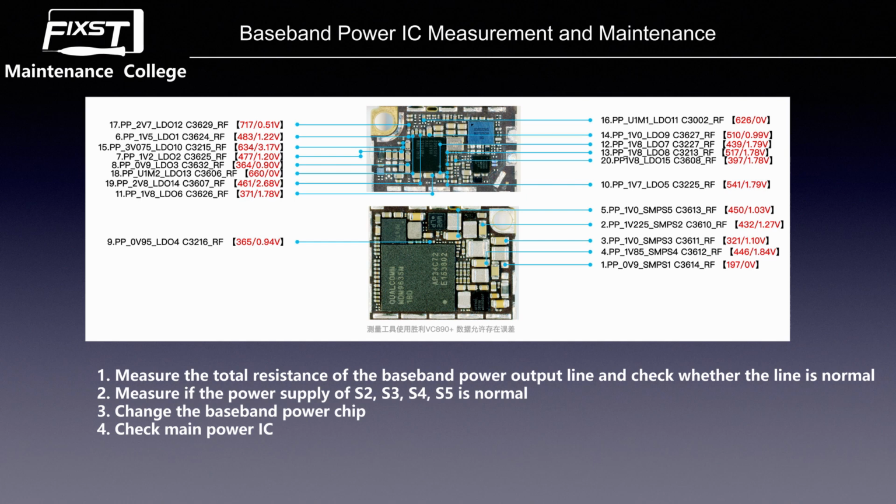We need to test S2, S3, S4, and S5, whether all the power is normal or not. And then we need to change the baseband power IC. If it still doesn't work, we need to check the main power IC, check the PMU.